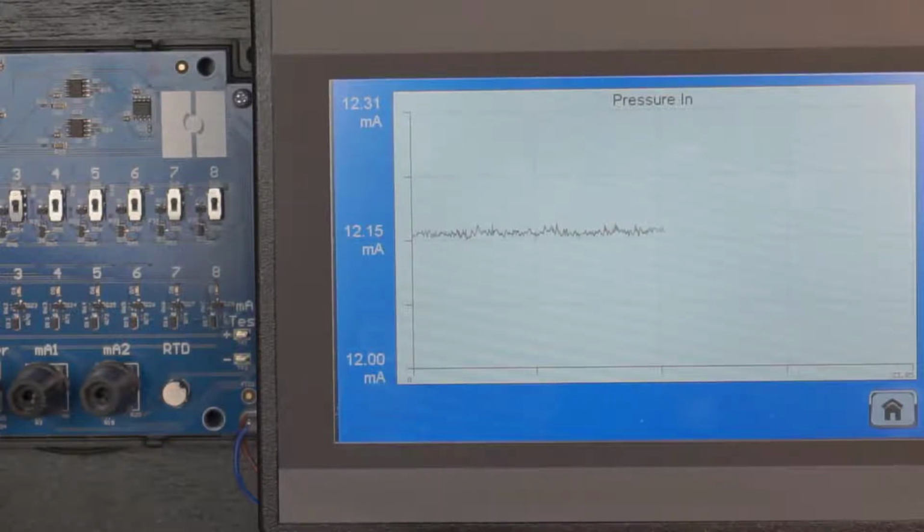So it should be obvious, though, from looking at this signal, how much we have narrowed down the swing and how much we've added stability to this signal. Before I added this filtering, it wasn't uncommon for us to get values a quadrant above or a quadrant below, or whatever you want to call that screen quadrant there on my graph. It wasn't unusual to get values that occasionally would get up towards the top of the next quadrant or the bottom of the previous quadrant. As you can see here, we're hugging the center pretty well. We could make it more stable, but we would do that at the expense of response time.